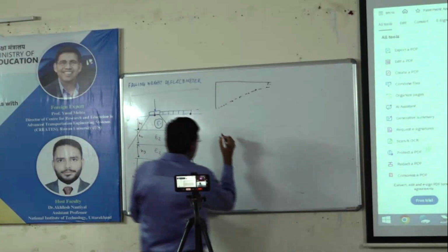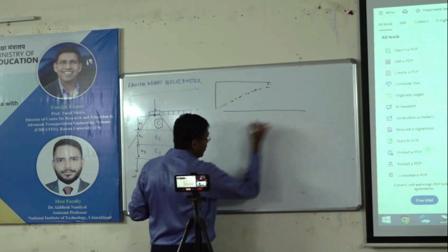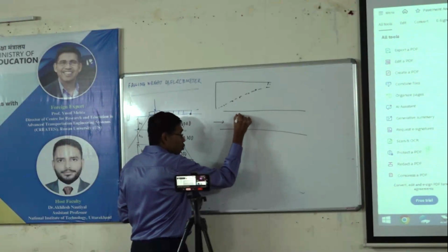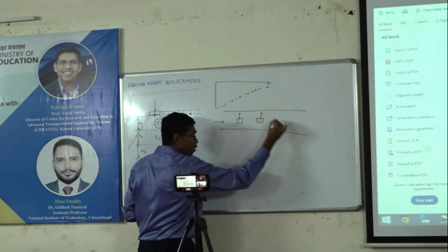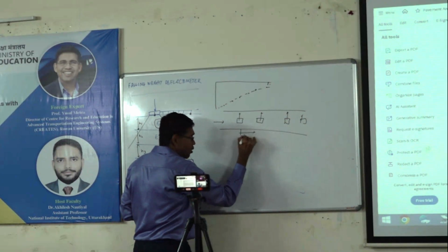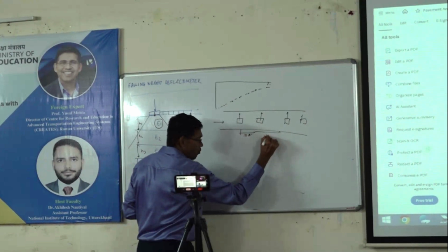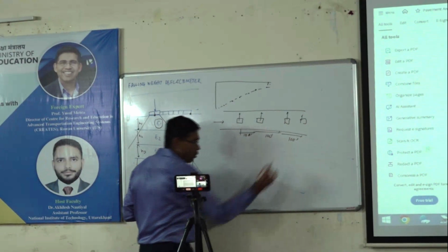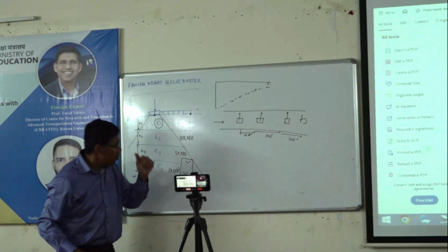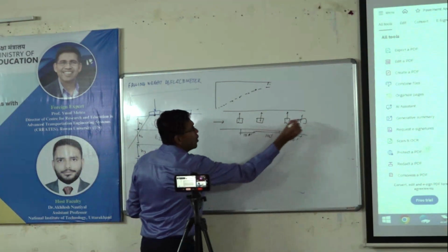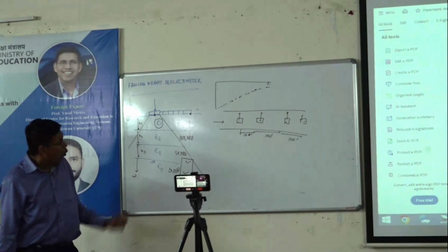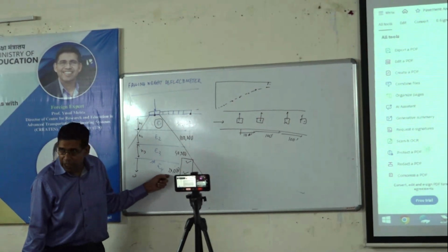If I were to take, in this location, one FWD, 2 FWD, 3 FWD. These are, let's say, 100 feet apart. Okay? This is along the plan view, along the roadway. Question here. If I hit here, right? Barely 300, 400 feet apart, correct? What are my chances my subgrade will change considerably within 400 feet?